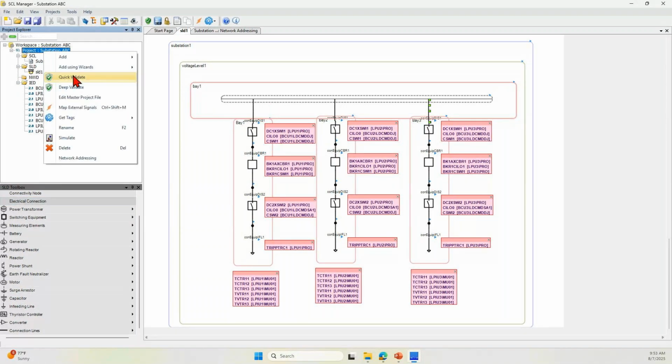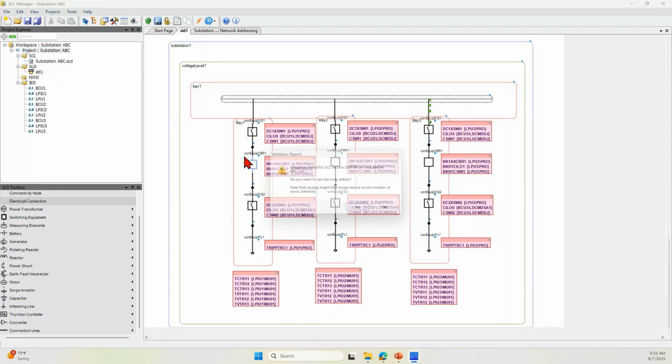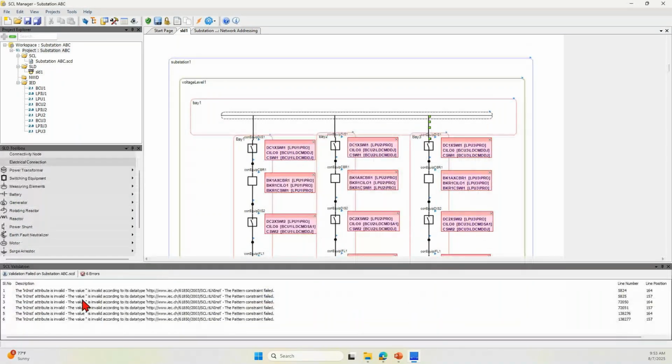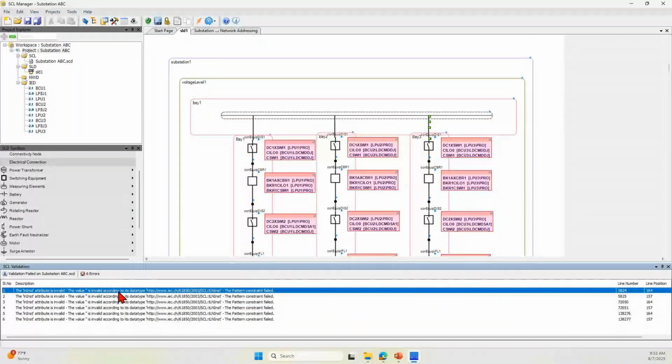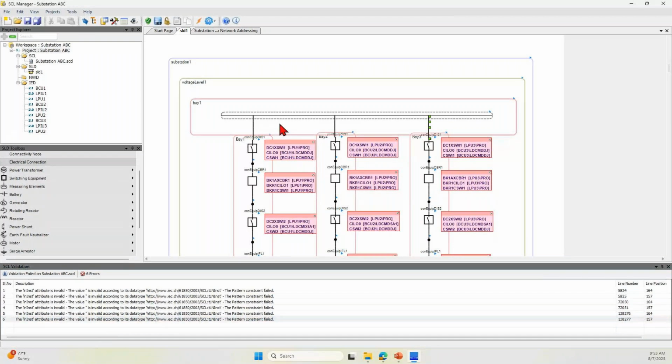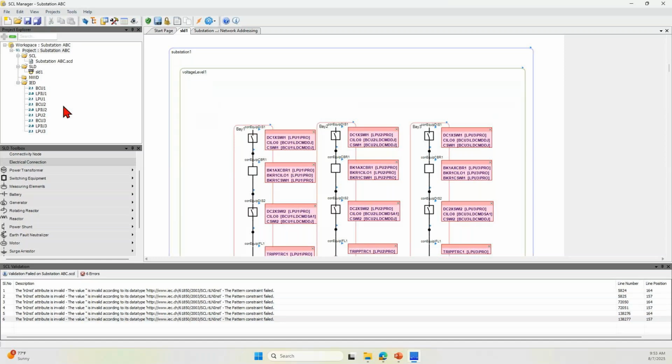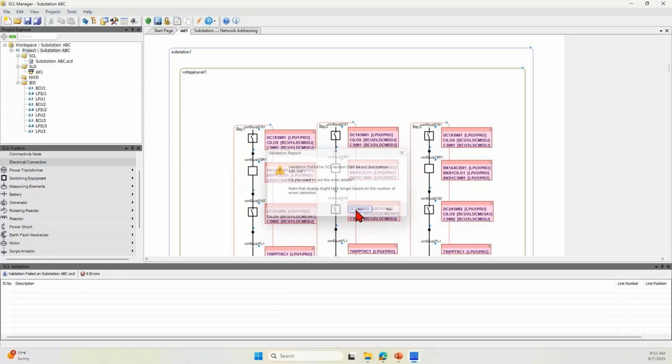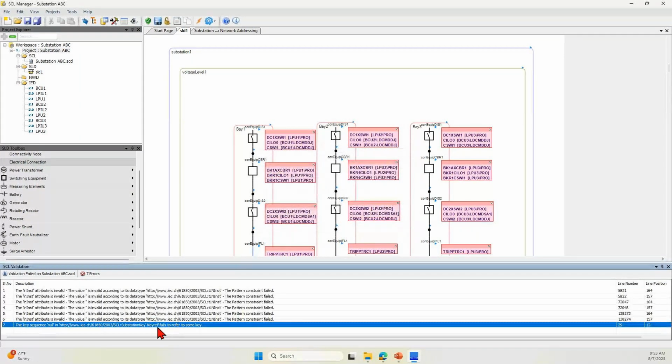And if you validate, we should not be seeing this error. Yeah, we don't see that open terminal error anymore, right? So yeah, we should have cleaned these errors while saving the Bay template. These errors are repeating from the other one. But the other open terminal error has gone after import. If you did not have this configuration, then it would be giving you that open terminal error. So you can see that this error is present here, right? So I was referring to this one.